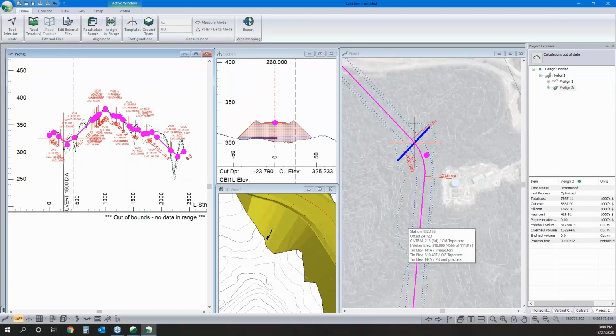So with the earthwork optimization, the driver is going to be to minimize material, or minimize your cut, minimize your fill, and minimize movement. So that relationship stands for any kind of earthworks construction. So we've assigned the constraints for your alignment, and whatever you use for values, it's going to want to minimize those.